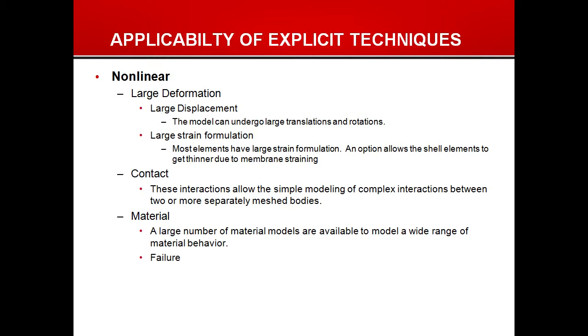Well beyond the linear elastic realm, we can deal certainly with all the standard engineering materials like aluminum, steels, titaniums, where we have an elastic plastic response. The other thing that I like to bring up when we talk about materials is the fact that these tend to be short duration events, we've already said that, and we've also said that they can be large strain. We have a large strain in a short duration, and that's going to give us high strain rates. We have techniques to deal with these high strain rates.